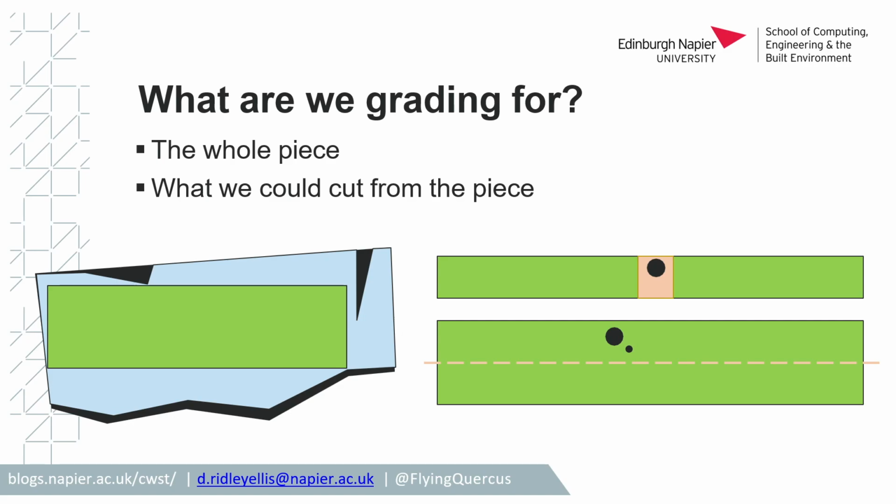So when we buy timber from the sawmill, we would normally buy it graded, and it should be stamped on the timber what the grade is. I think I've already shown you that. I have. And it's already stamped on the wood. If it's not been stamped on the wood, we have to do calculations for the structural stability, strength of that, a slightly different way.